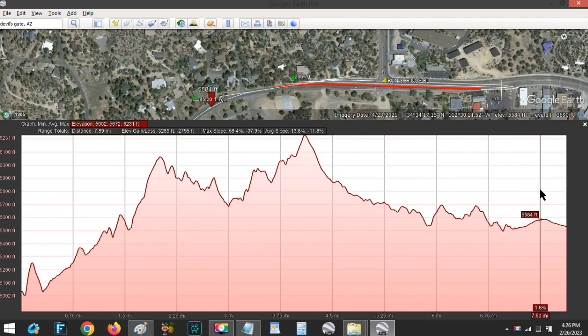And I have the thing as being about, so there's room to get from the vertical curve that is centered right where that red arrow is. And that point of vertical intersection would be 5510. 5,510 feet.